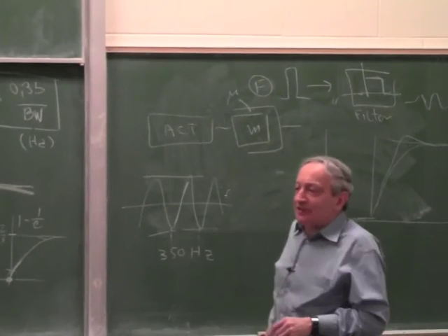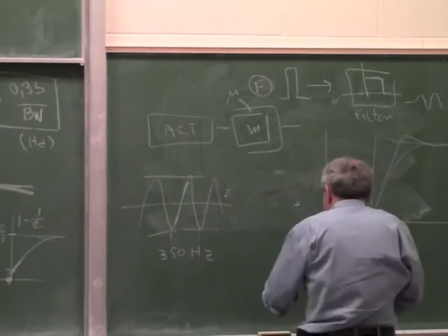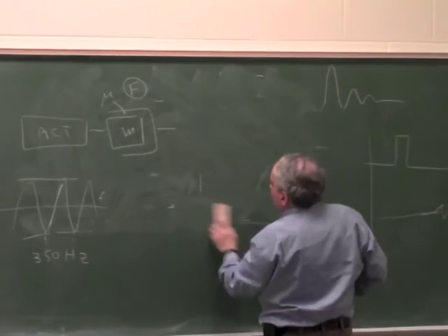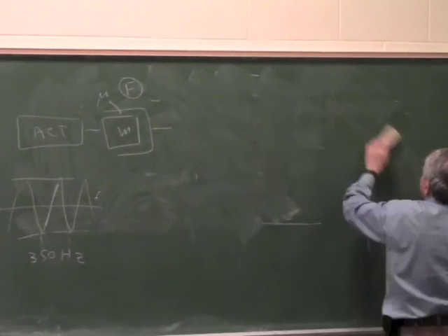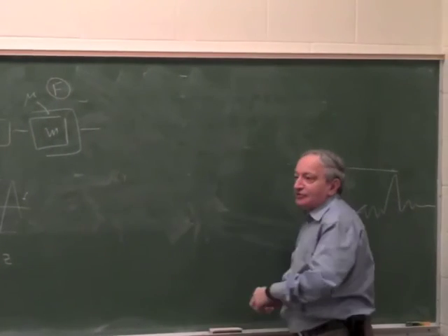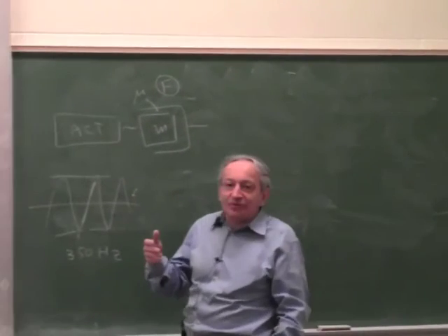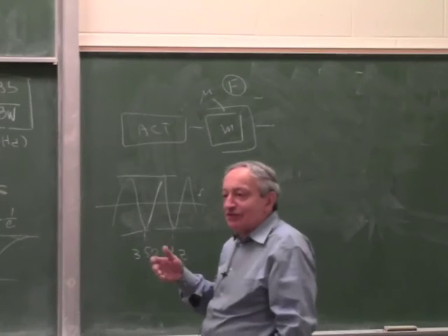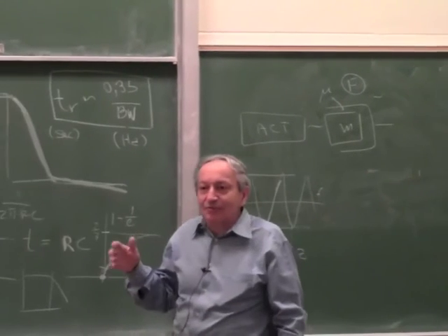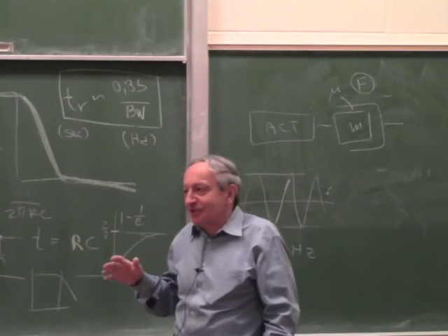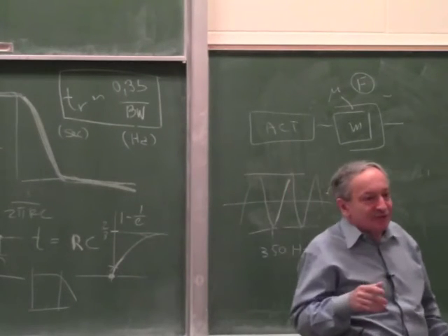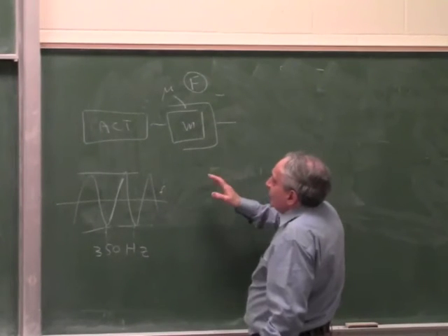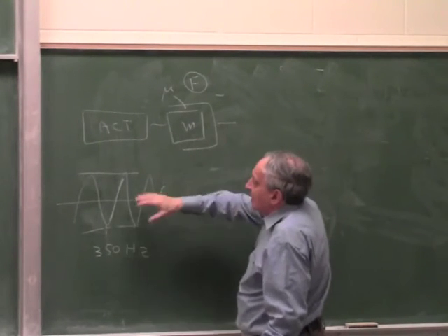If it's a complex question about power, the easiest way is to get to it through the energy. I showed you the same approach when we derived forces. When we analyzed the force of the actuator, I also showed you how to derive it from energy. In a moving iron actuator, we derived the force from the energy. So in most complex problems, it's easiest to start from the energy and derive the force, the power, everything from the energy.